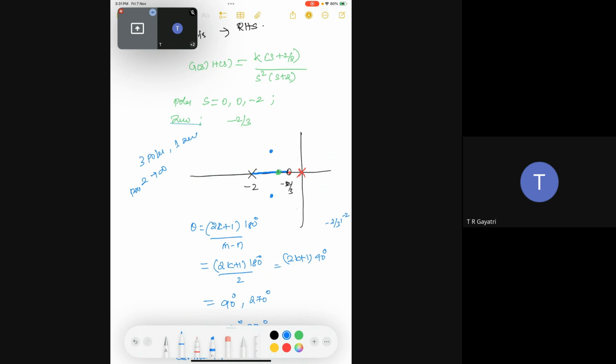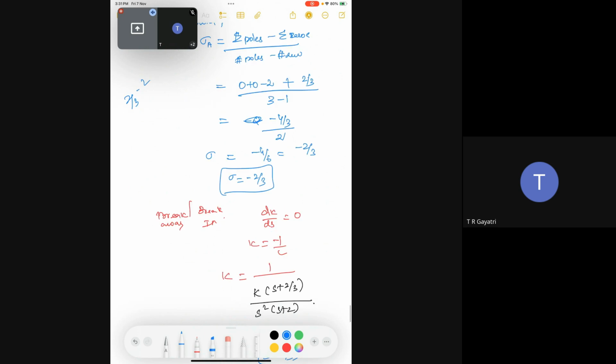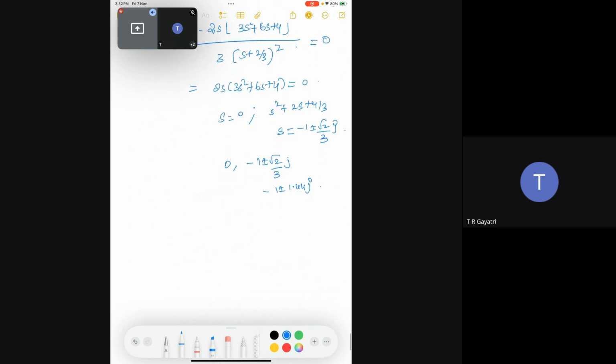How come it is not coming inside 0.4? It is included, no? Oh, okay. Since we don't have any conjugate poles, this break-in point is not valid here. So we are going with only this. So I'm going to take only s equal to 0 as my breakaway point.